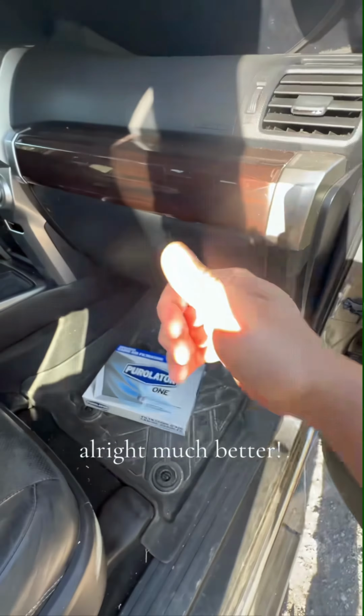You just simply hook up this dongle to your car or truck, download the app, and you're good to go. One thing a lot of people ask me when I review a scanner on my page is, hey, can that thing read ABS codes? Well, a lot of the handheld scanners I've reviewed on my page are just engine code readers. But as you can see here, this one's doing an all-system scan. So yeah, this one can read ABS fault codes, but it can also read fault codes in all these other modules. To look closer into the fault codes on this truck, just click on Report. And there you'll see the fault code numbers and description for each module that had logged faults.